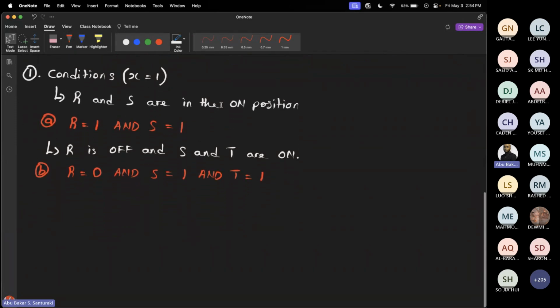What do we do? We move on to step 2. In step 2, we make use of our truth table to reverse engineer the logic we want. Remember last week, the truth table shows all the possible inputs and all the possible outputs of a circuit. Now we're designing a circuit which we don't know what it looks like, but we know how we want it to behave. So we can create a truth table and fill it up with the values we want and then reverse engineer the logic. Allow me to demonstrate.